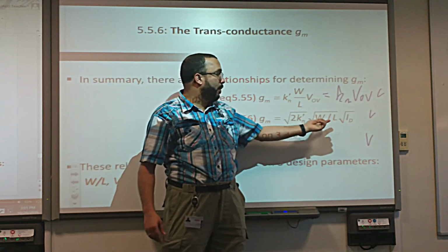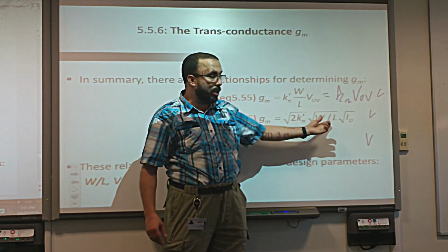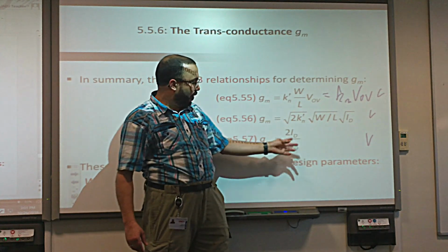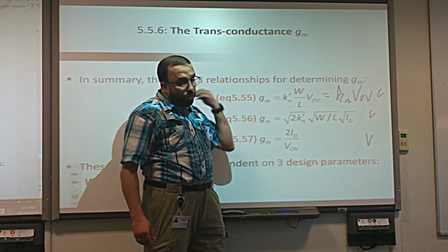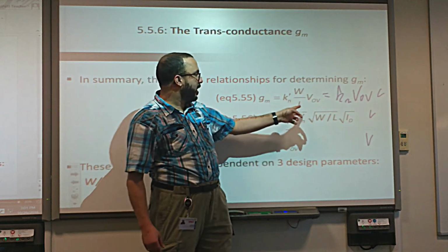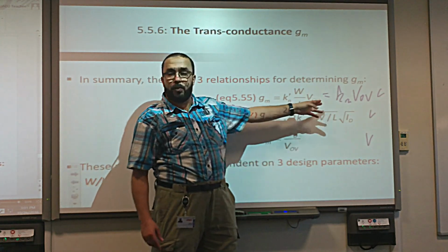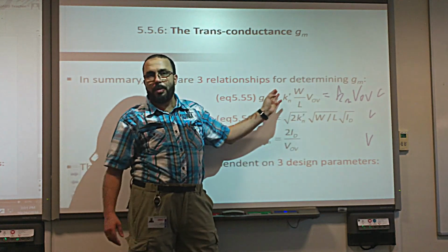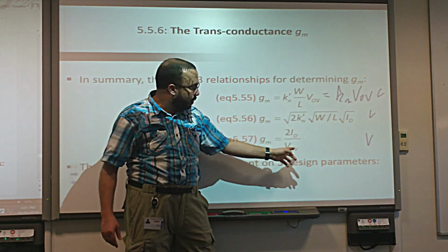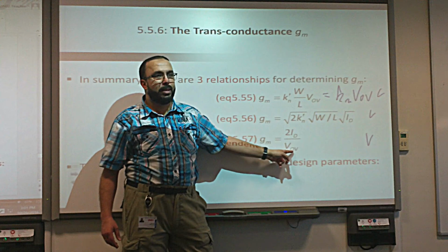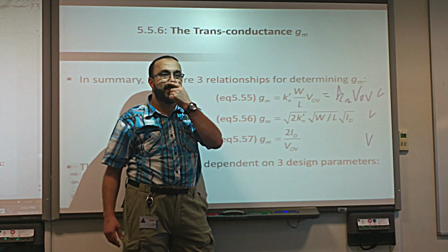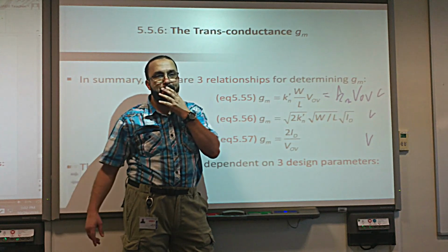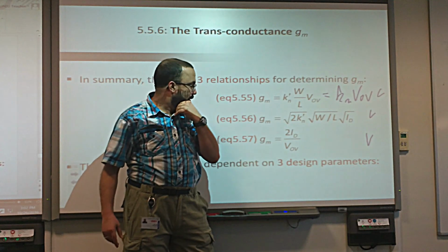Sometimes I don't know how the transistor is made, meaning the dimension of the transistor. So I will use the overdrive and the current alone. Yes or no? But let's think about something really interesting. If we increase the overdrive, GM increases or not? Yes. But what about here? Does it decrease? No. It's over 2. It's half of the overdrive.